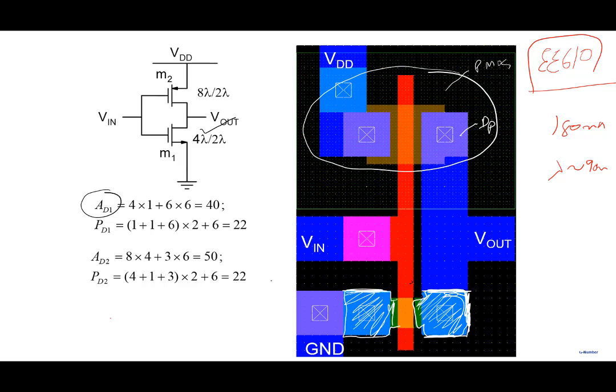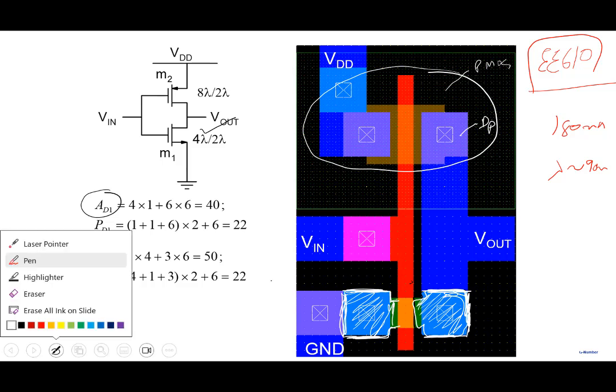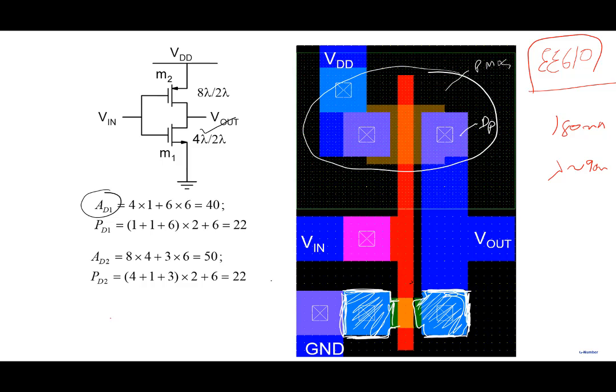I have to go towards the perimeter of this part here, here, here, and here. Then only I will get the perimeter part. The boundary of the source, the boundary of the drain will give me the perimeter part. So the point that I'm saying is, you have to do the layout, and only then will you get the source area and the drain area. Then only can you compute the capacitance. You need these things to compute a very important capacitance, which is drain to body.